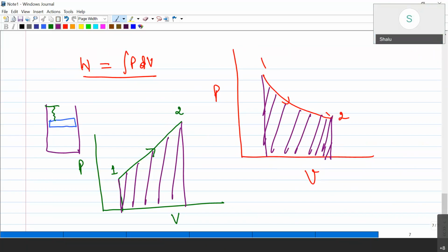Similarly, what happens with carbon dioxide? Obviously carbon dioxide is in the gaseous state. When it is in the gaseous state, we require two thermodynamic properties to specify its state. Majority of the time, when property tables for gases are given, we have properties at different temperatures, and at the top it is written that this table is applicable for, say, P1 pressure. Then for P2 pressure we will have another table applicable. From that we can determine the value.